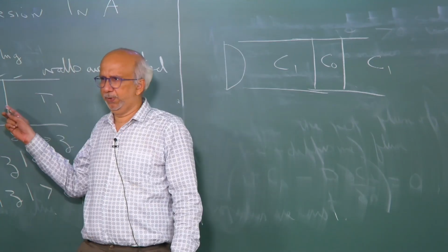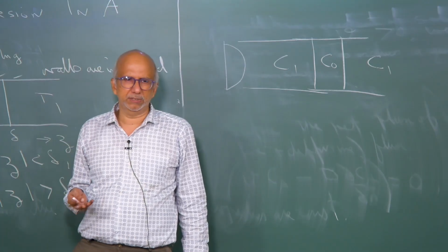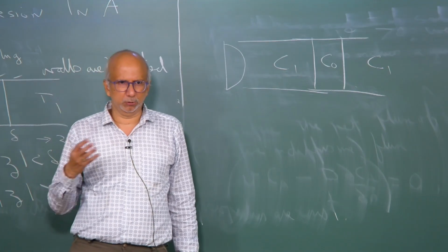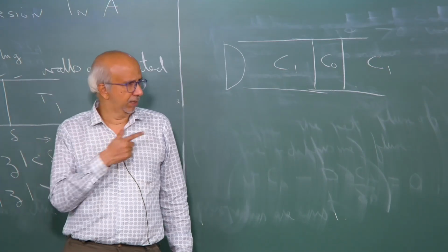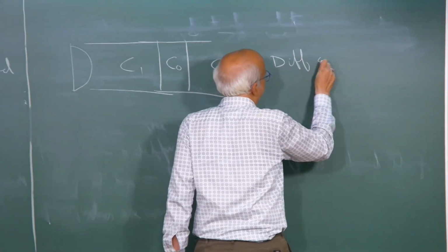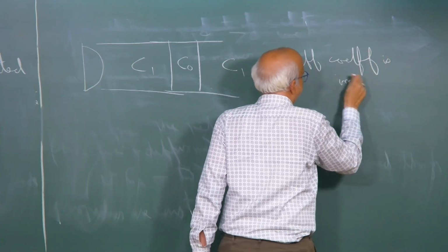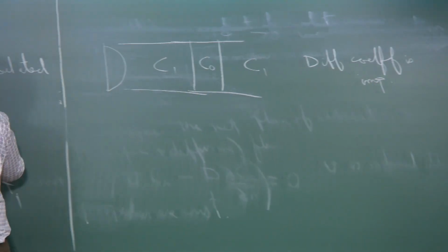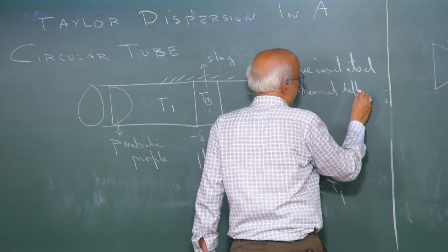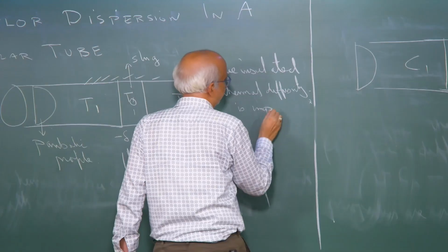Here alpha is going to be, let us say the fluid is the same, so your Reynolds number is the same, your pipe is the same, properties are the same. The only thing which is going to be different between this species and this is that here the diffusion coefficient is important, and here thermal diffusivity is important, okay.